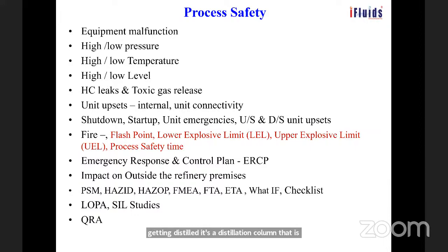As this reaction is taking place in the reactor in the presence of catalyst, coke gets deposited. The catalyst having the deposited coke becomes inactive, so it has to be activated again. So it goes to the regenerator, and there the coke gets burnt in the presence of oxygen at a high temperature, and the activated catalyst again comes back to the reactor. It's a cyclic action. I hope you understood. And the flue gas going out from the regenerator contains some catalyst that gets captured. Plus, that flue gas is at a very high temperature, so the heat is recovered.